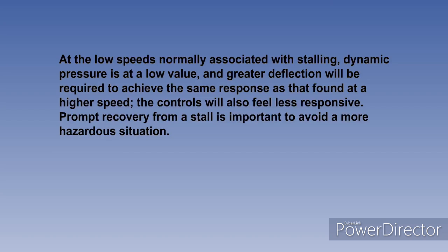If an accidental stall should occur, it is important that the recovery is effected before the process develops too far, with a large wing drop giving a high rate of descent or possibly leading to a spin.